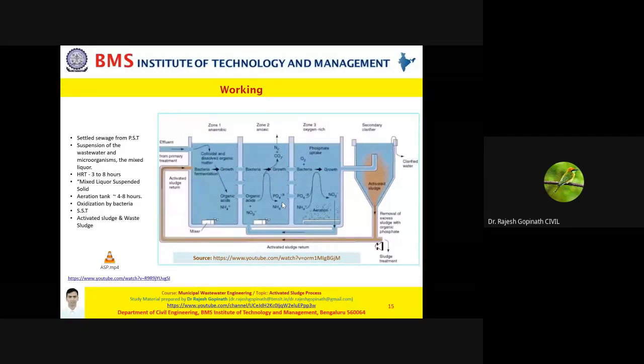Now, this process would take roughly 4 to 10 hours. In this 4 to 10 hours, the bacteria are getting the opportunity to break down the matter. Aeration is constantly happening, air is constantly being mixed, oxygen is constantly entering into the system. After this 4 to 10 hours of retention, the treated wastewater enters into your secondary clarifier.